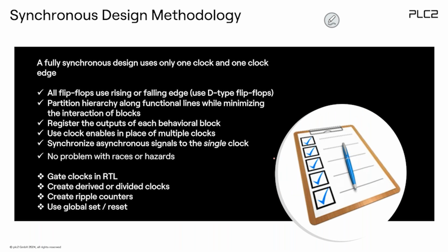The synchronous design methodology is actually just a definition: all flip-flops use the same edge, rising or falling. Of course, you could also do something like this, using a rising edge here and a falling edge here. I don't think it violates the concept of synchronous design.